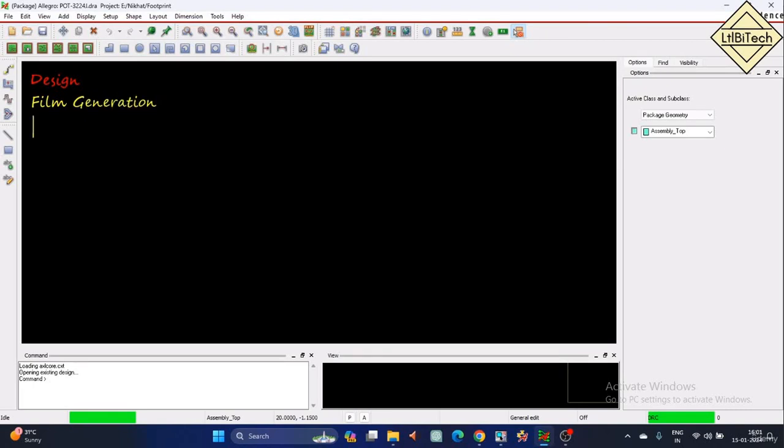The third point here is the substrate preparation. In the substrate preparation, the base material, often fiberglass reinforced epoxy, known as FR4, is cleaned and prepared, and it may come in sheets or in panels depending upon the intended PCB size. So whatever the size of the PCB, we need to prepare the substrate, which is FR4 material. On top of it we do the copper cladding.